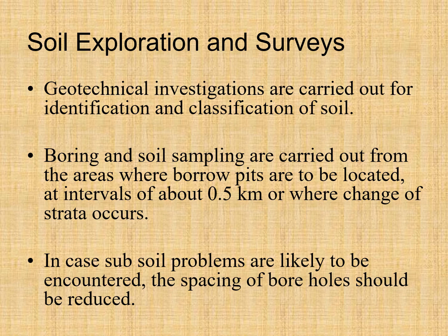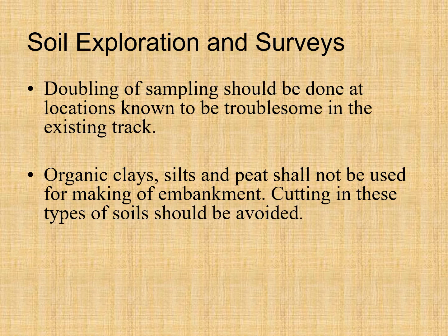In case subsoil problems are likely to be encountered, the spacing of bore holes should be reduced. Doubling of sampling should be done at locations known to be troublesome in existing track. Organic clays, silts and peat shall not be used for making of embankment. Cutting in these types of soils should be avoided.